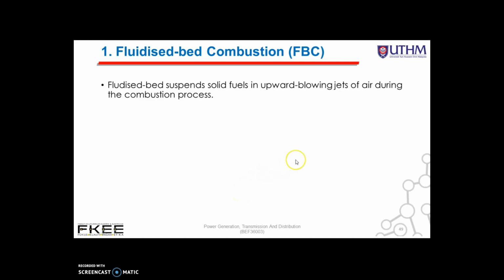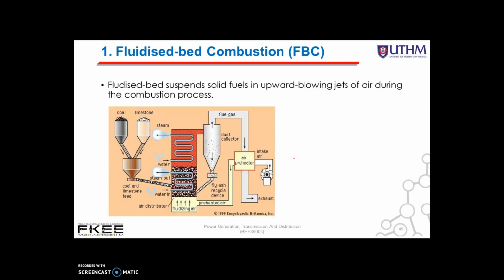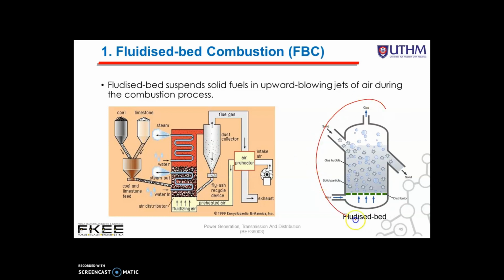Okay, the first method is the Fluidized Bed Combustion, which is the FBC method. In the FBC method, the fluidized bed suspends solid fuels in upward blowing jets of air during the combustion process. So you can see here, this is the fluidized bed. The result is a turbulent mixing of gas and solid. The tumbling action, much like a bubbling fluid, provides more effective reactions and heat transfer. So instead of the usual combustion process, it uses the fluidized bed method.